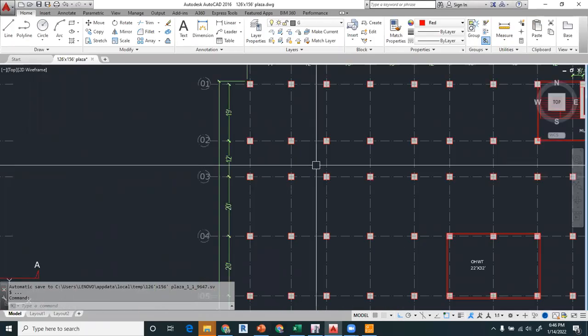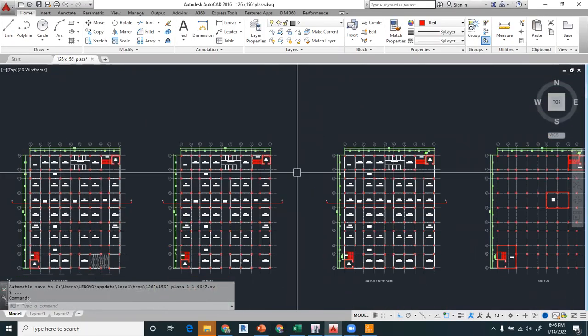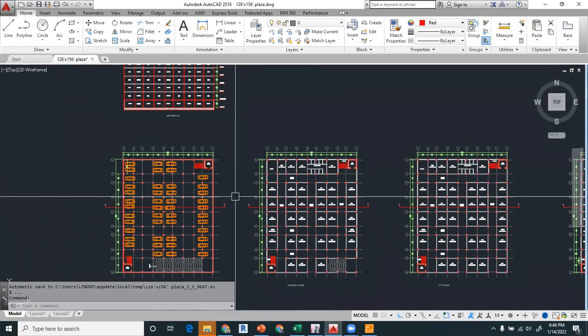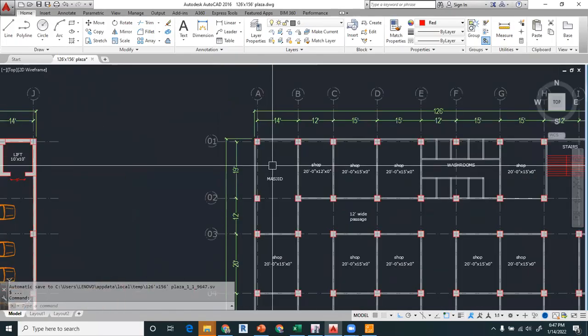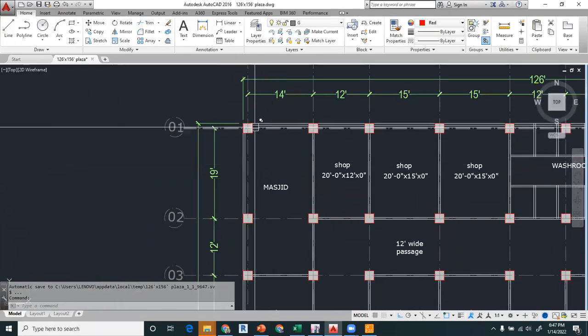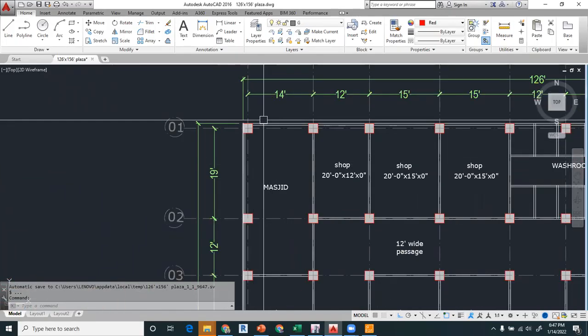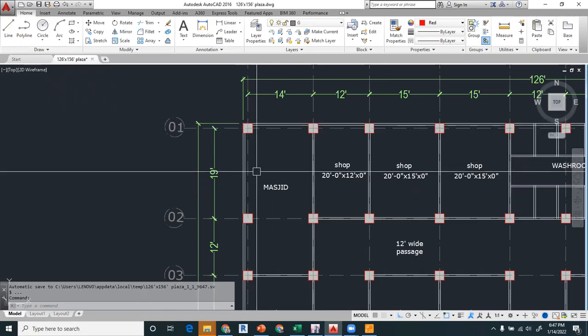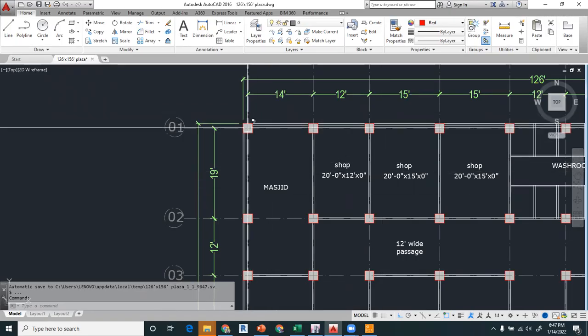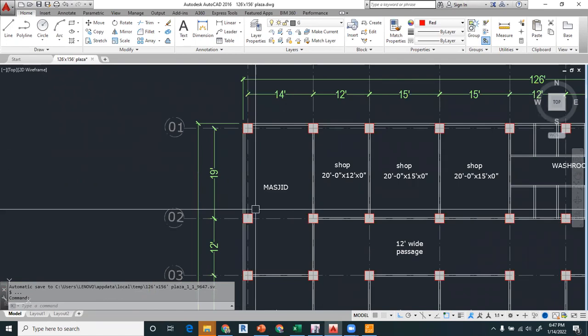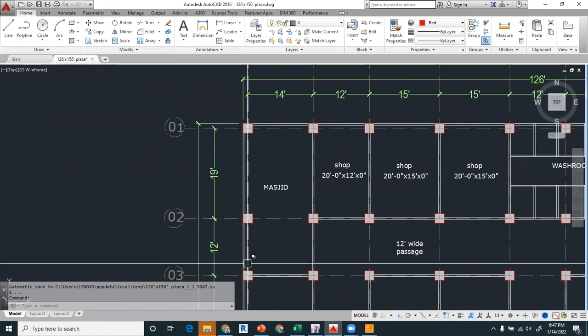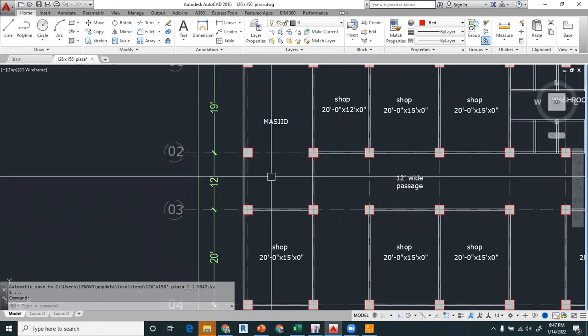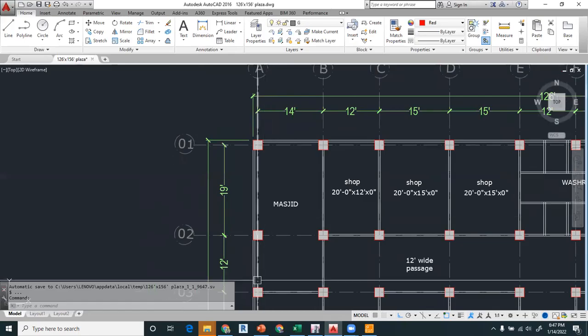So we will select our region if we want to calculate the depth of the beam. So we will select this one. We will say that we want to calculate the depth of this beam, that is this end is dead and this end is continuous, because this beam is continuous from these 3 bays and so on. So this end is dead and this is continuous.